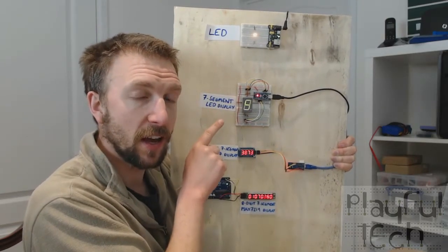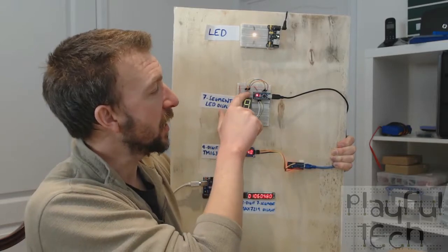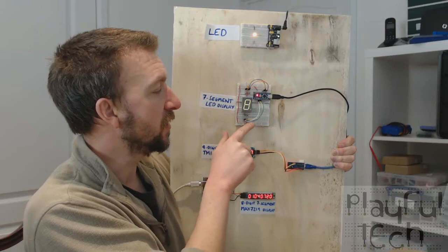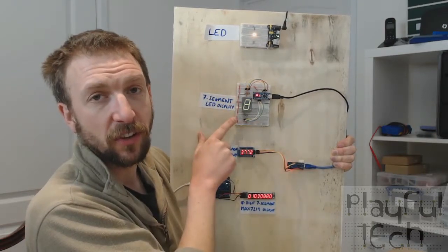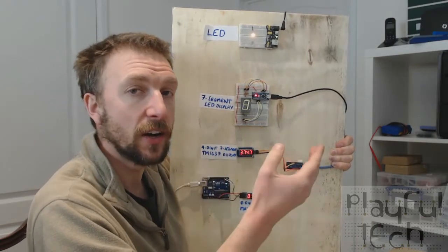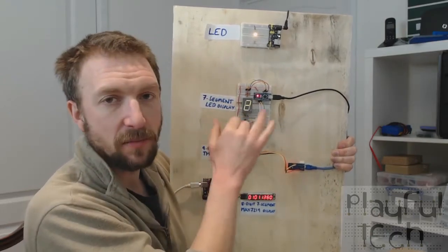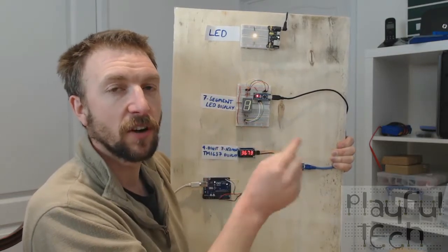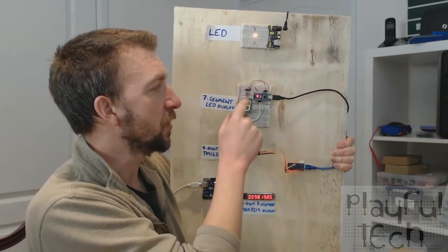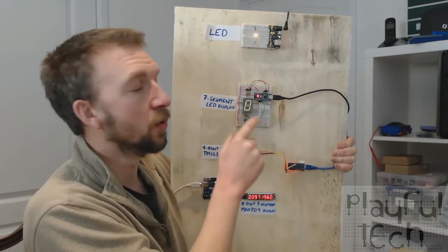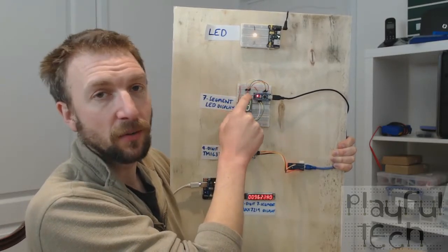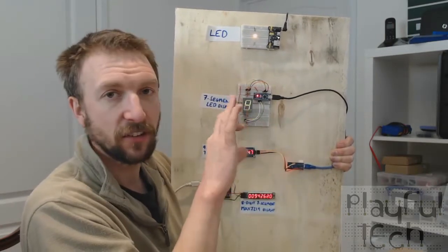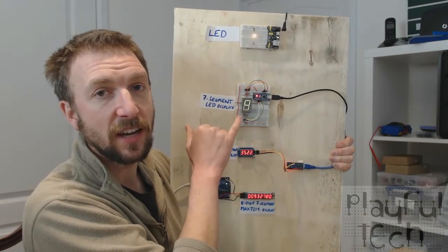If it was a common cathode instead, this center pin here would be ground, and then for each of these cables here, if I wanted to light the corresponding segment up, I'd send a digital write high. So it's effectively the same wiring internally, it's just everything's been reversed. You're either sending a high signal, which goes down a common ground, or there's a common source of 5 volts and you're sending individual grounds for the signal to go through. So it's just that the current flows in a different way through the LED segments.